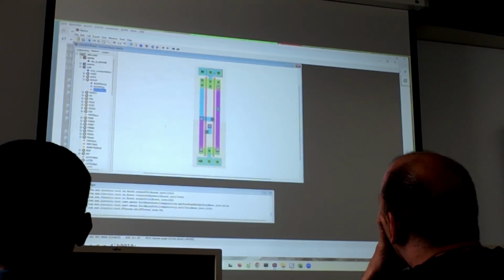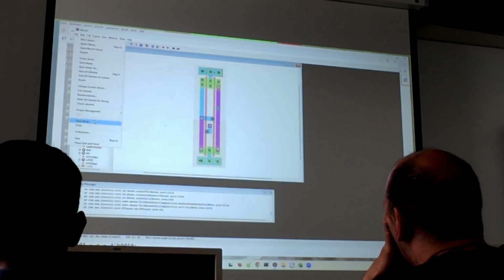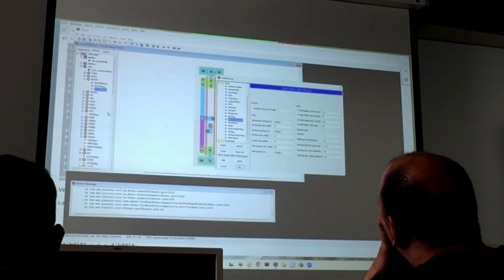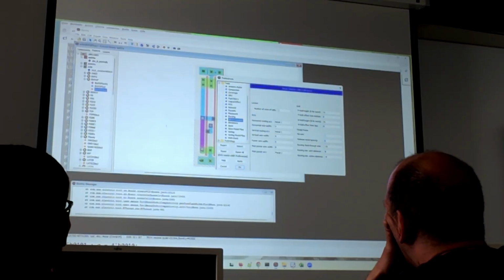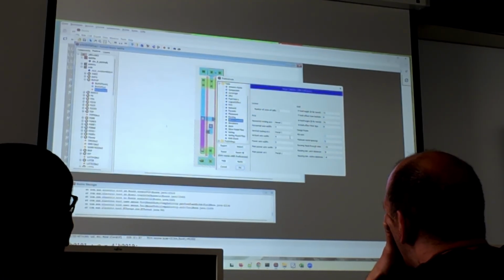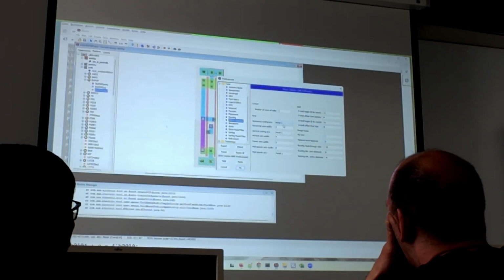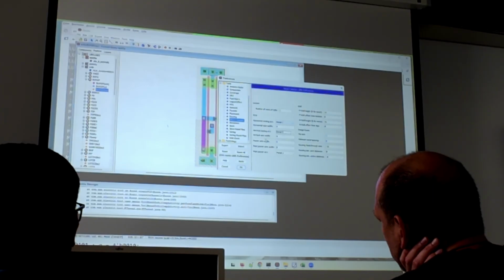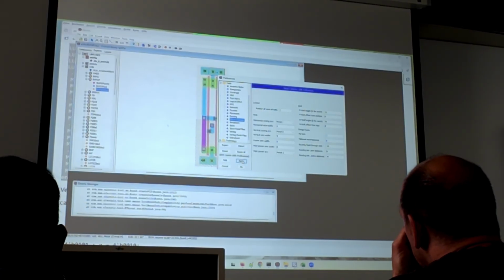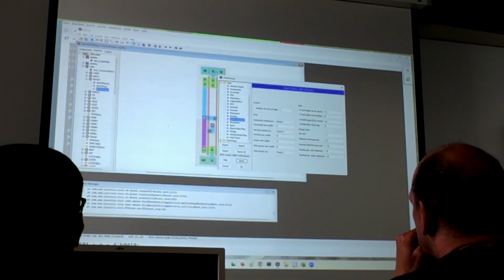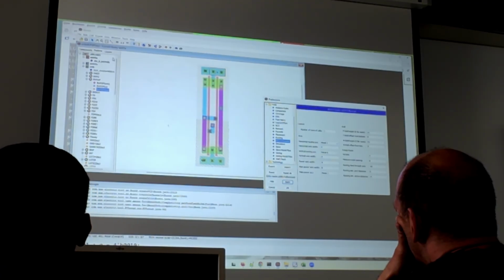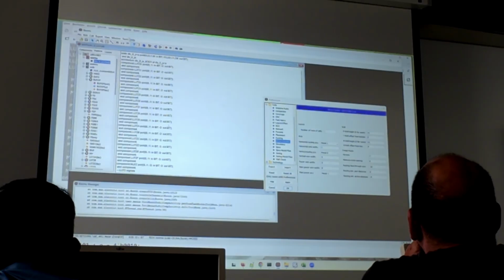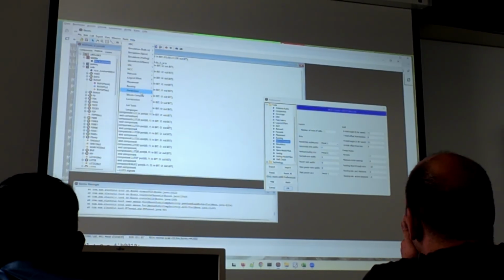Good. So let's see again. Preferences. Now I have metal 1, vertical routing metal 2, number of rows in the cell is 1. Okay. So let's try this part again, to see whether we can get this silicon compiler.